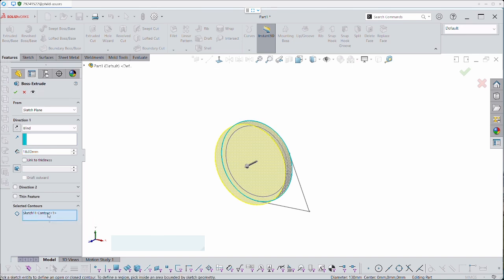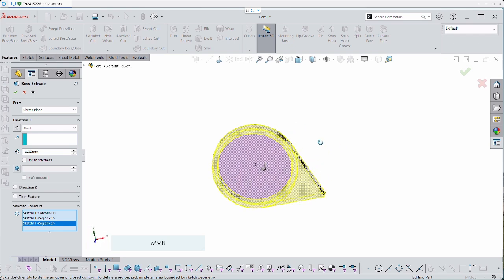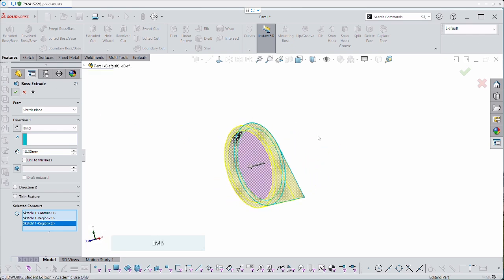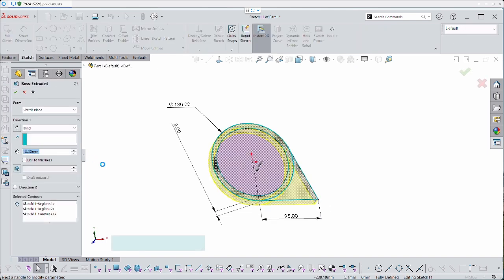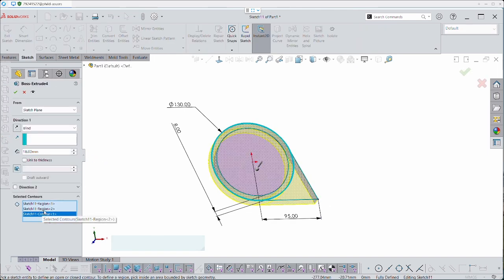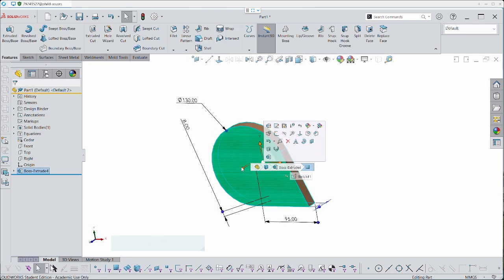Inside this blue box, once I activate it, I can choose other parts of the sketch and deselect certain parts. So at the moment, I'm going to get sort of a ring-shaped item. Okay, and I can just go back in here and say, no, that's not really what I want. I can just select that middle bit. Okay, and then this is being extruded 10 millimeters.